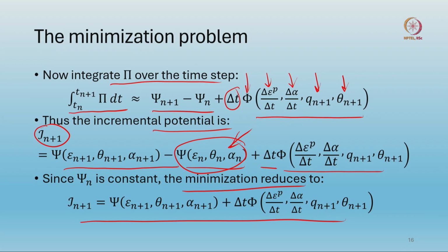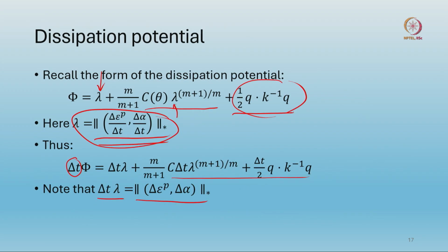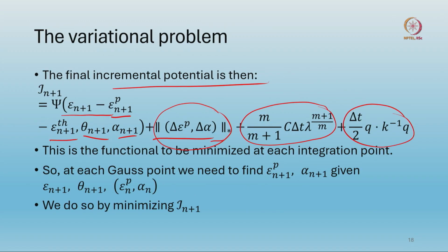But before that, we do the local update, in which we do not integrate the rate functional over the entire body, but consider it only at material points, typically the Gauss points of integration in your finite element framework. So this is the rate functional in incremental form written at a specific material point.